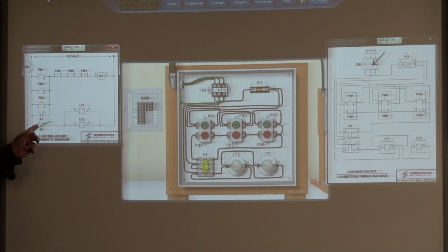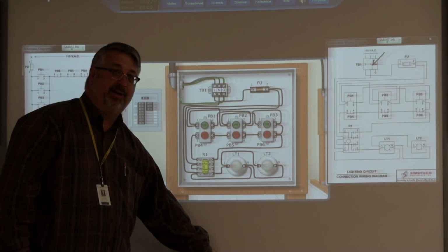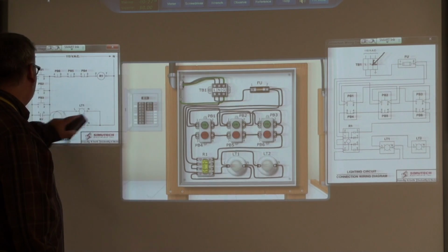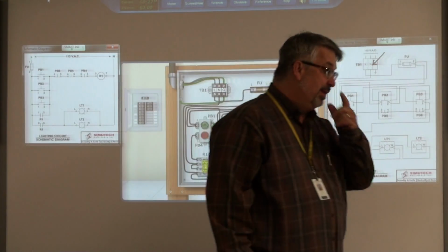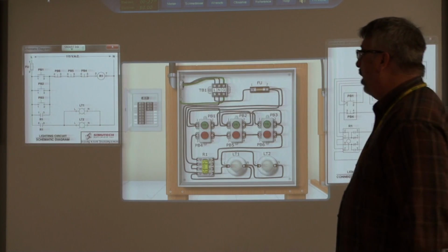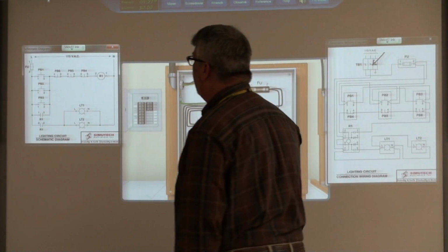Right. This contactor is welded shut and it couldn't care less what the relay's doing. You'd have to flip the breaker. Yeah, that's what I was thinking. You've got a path, no matter what. But if you break it on the first R1 press, it wouldn't engage. Not on the second, right? Because your R1 line would stay engaged through the second.